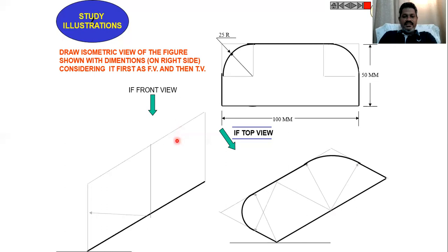Then join this intersection point and midpoint, and similarly join this midpoint and this intersection point, and this as radius. Draw a line like this. Draw an arc like this to connect these two midpoints with this intersection point as center. Draw an arc that is going to connect the midpoints of the two sides of the square like this.